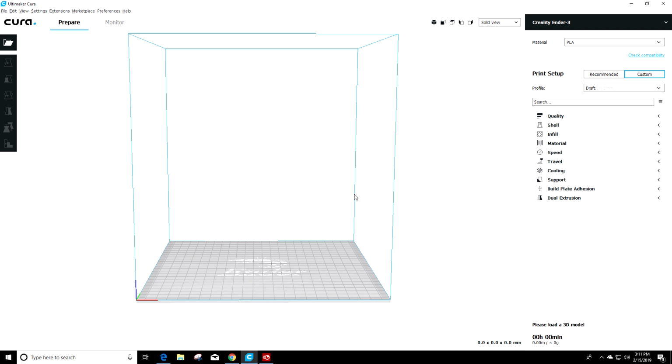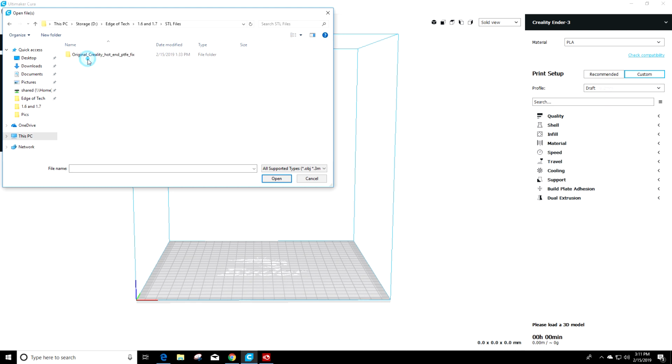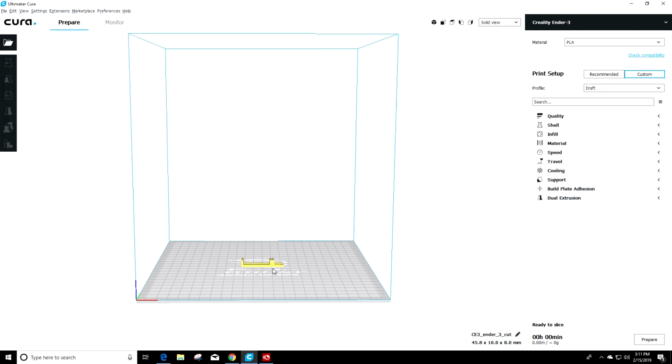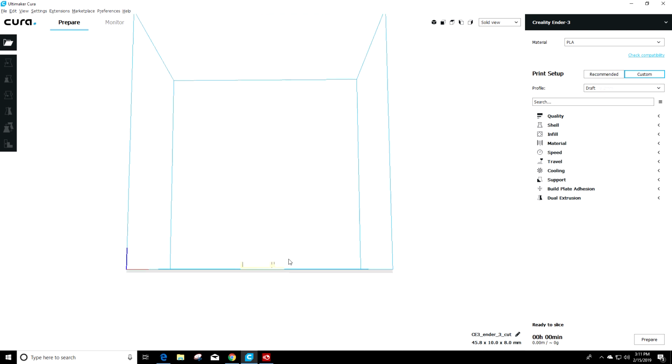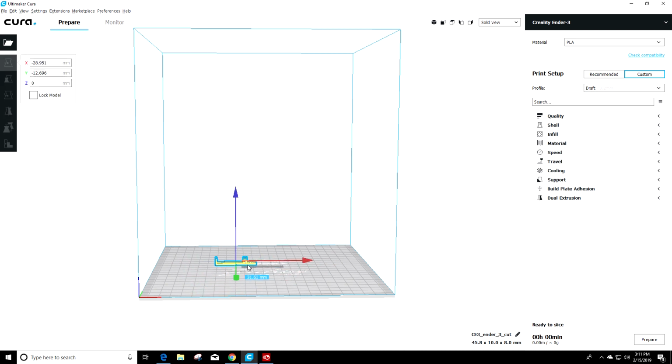The next thing we want to do is go ahead and get our STL file, the model we got earlier, into the slicer and slice it to get our Gcode file like we talked about earlier. So we're going to go to Open File. I'm going to go to where we stored our file from, and I'm going to look. Remember I said I had an Ender 3, so I'm going to go ahead and select Ender 3 and hit Open. So what this is going to do, it's going to show us our model, what we want printed, in the middle of the bed. Now with the right click button, you can move this around and see it at different angles. You can also grab it and move it around on different parts of the bed if you want to do multiple of them or anything like that.